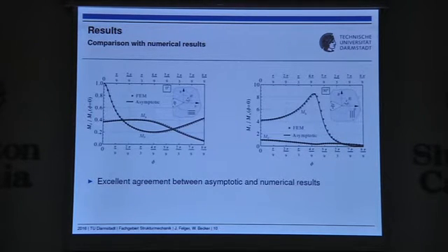Okay, now I would like to present some results, starting with a comparison between the asymptotic solution and numerical data. So we consider a notch plate under symmetric loading, and we performed finite element analysis using Abaqus with conventional thick shell elements. So on the left-hand side here, the bending moments are evaluated along a circular path close to the notch tip for a 0-degree fiber direction. So just one fiber composite layer. And it can be seen that there's an excellent agreement between the asymptotic solution and the numerical data for the 0-degree fiber direction and the 90-degree fiber direction.